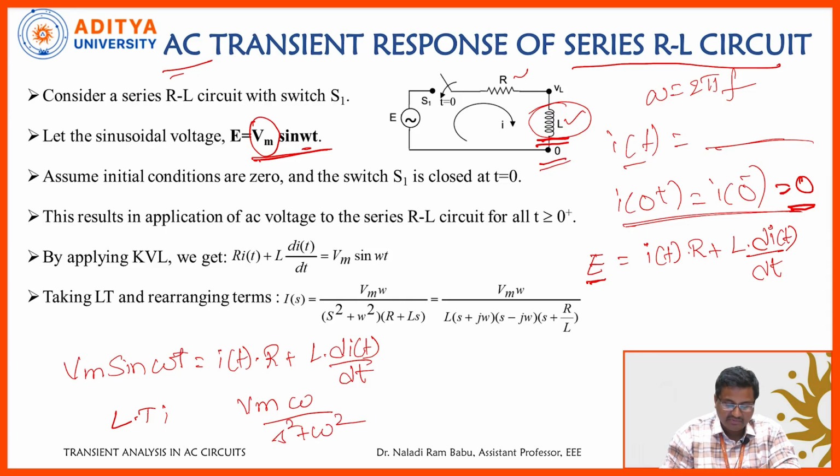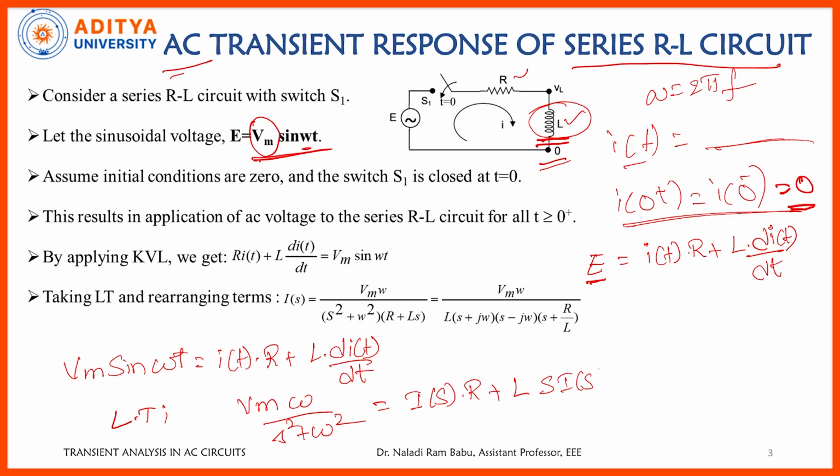I of t will be I of s, R is a constant so it stays as it is, L we keep constant, and di by dt is s into I of s minus I of 0. But here I of 0 is 0, so this term will be 0. Simplifying further, it will be I of s into R plus s L.